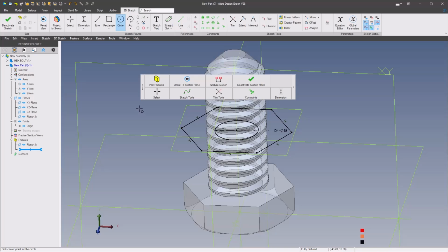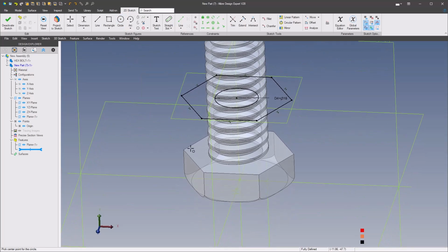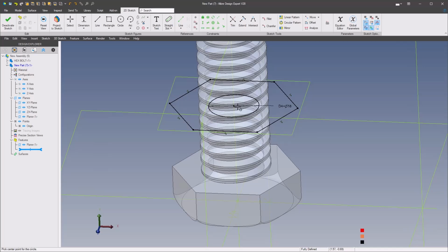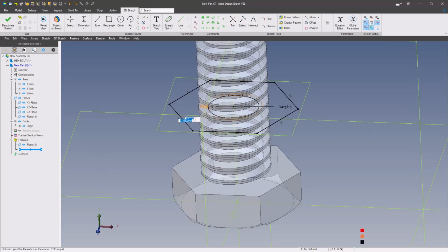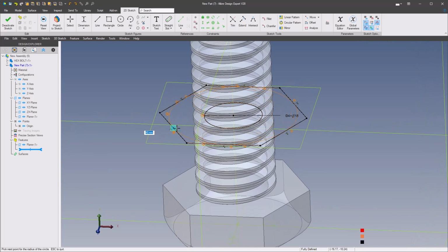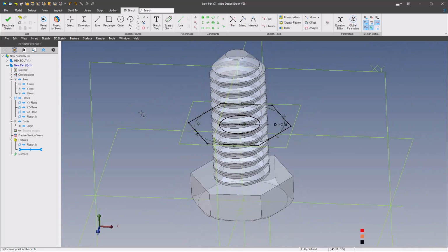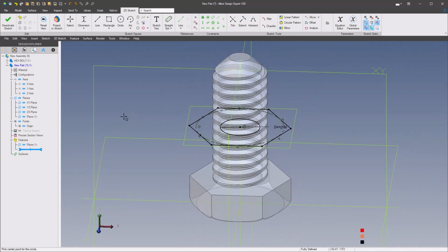And one more circle we need, and that's going to be a reference circle. Because we only selected the face, we cannot select the sketch that would have brought up our reference circle in here. So we grab our center point, drag out, and as soon as we manipulate the mouse so that we get tangent symbols on all of the lines, we click to place it, and now we're complete.